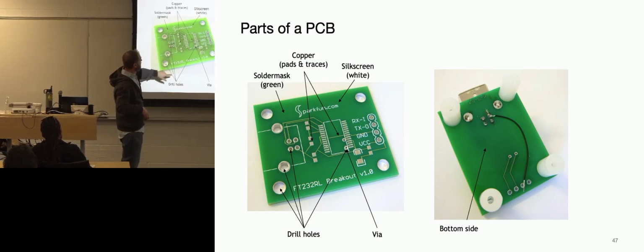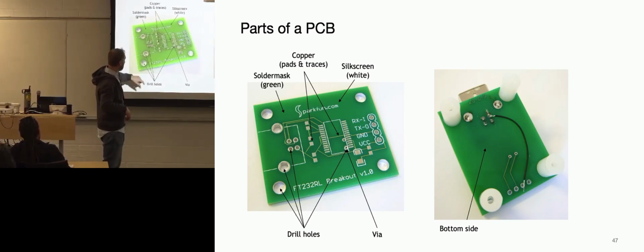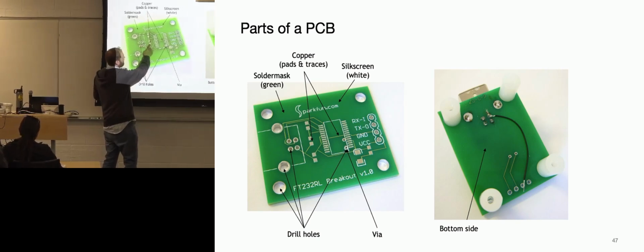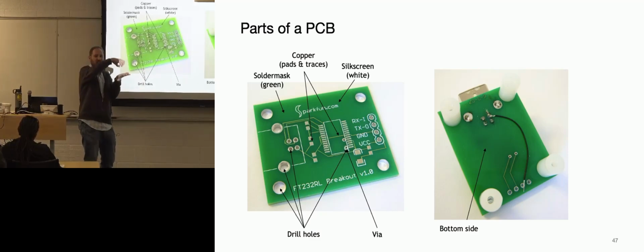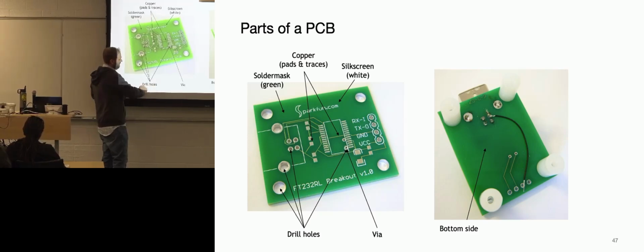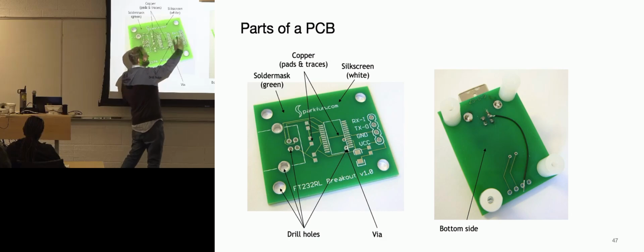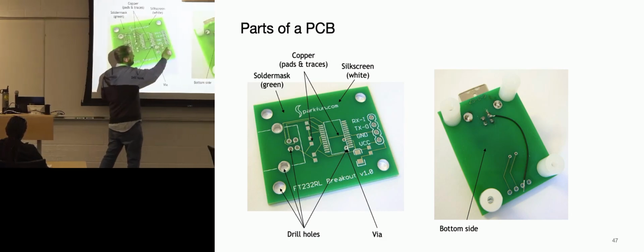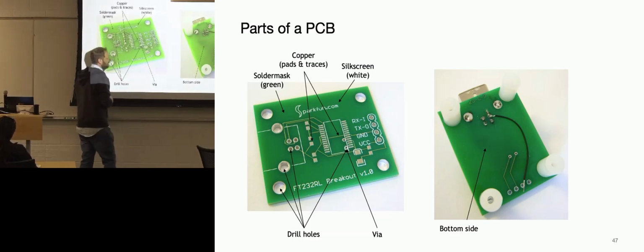This is kind of a typical PCB. On it you have, it's not vias, this is called a pad. So there's this terminology. Pads are things that you would put surface mount components onto. You could also call this a pad, even though it is a drill hole, but this is meant for, especially this one, a landing spot, in this case for 0.1 headers, and these would get put in here and soldered on, and this just happens to be a pad with a hole in it.